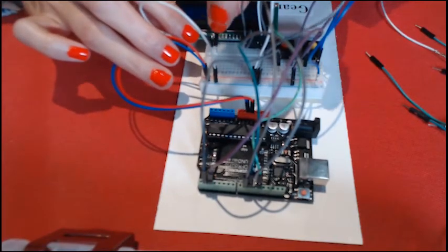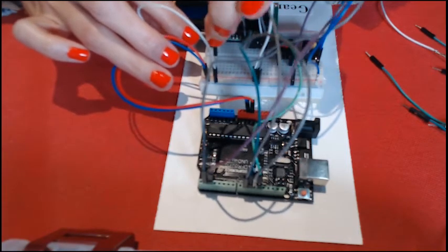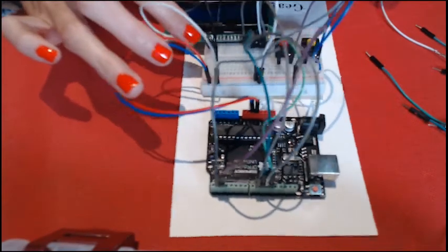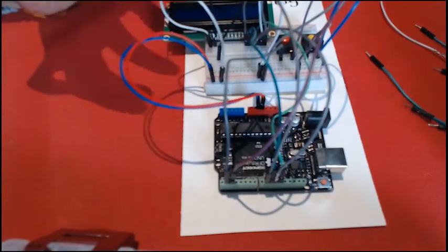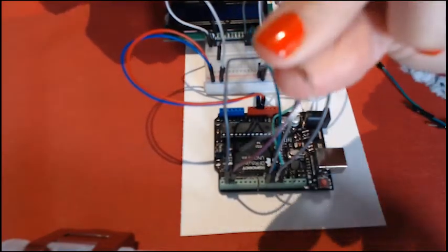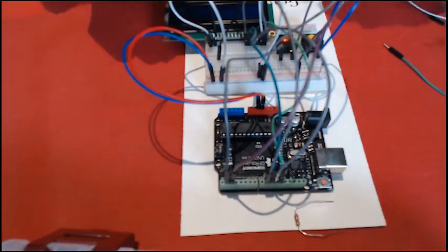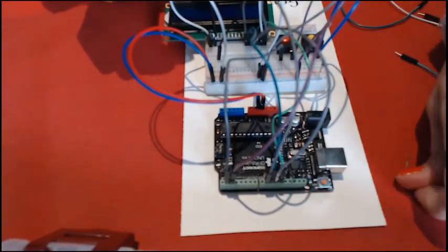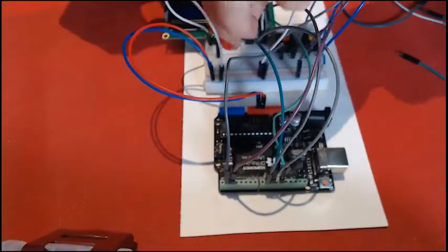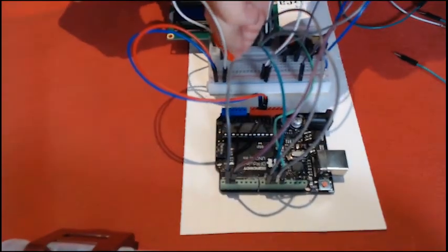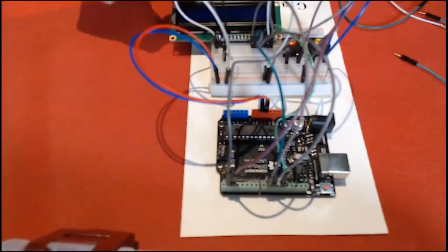The next connections that we have in here are the reading of data of our LCD. So we are gonna start with this one, the third one. This is our connection that goes to number 3. So we're gonna start connecting this one to number 3 of the microcontroller, which is in this section.